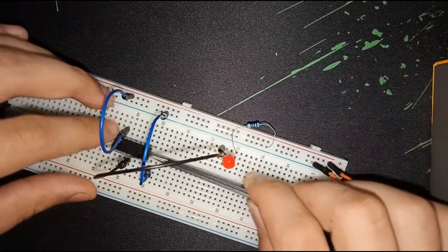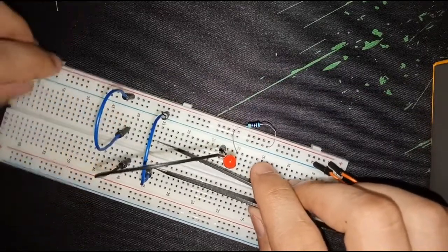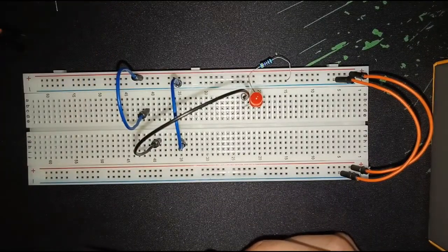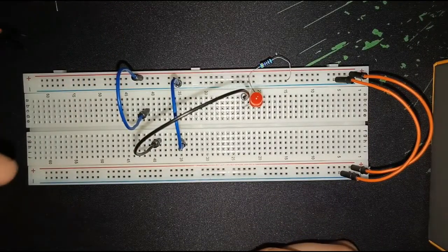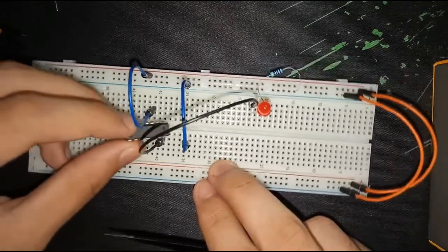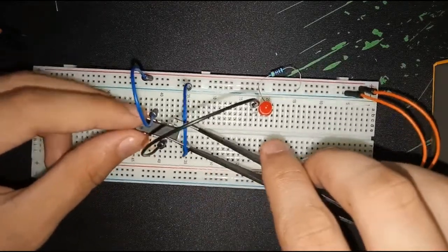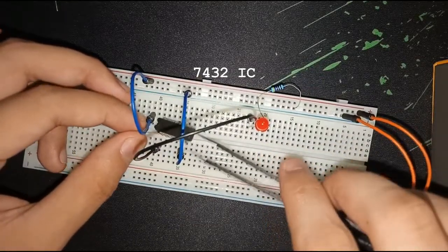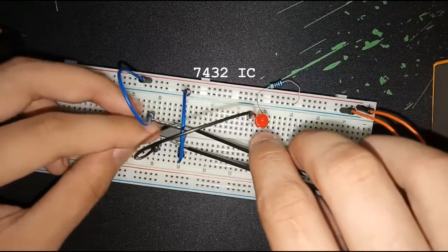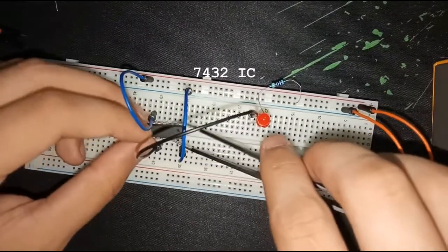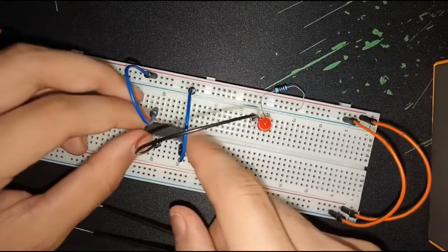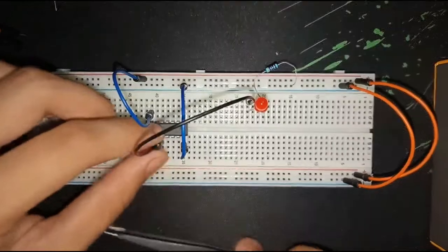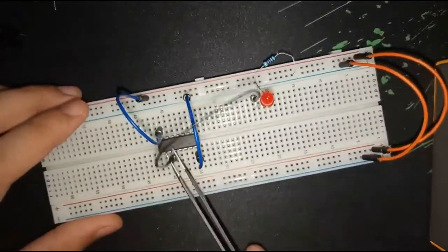So now let's proceed with the NOT logic gate, or the NOT integrated circuit, or the inverter. So we will replace it. It is still the same as the other logic gates, we still have ground. Your 14 and the 7 pin are ground, but the inputs are different because your inverter has a single input and output, meaning pin number 1 is your input and the second pin is your output.